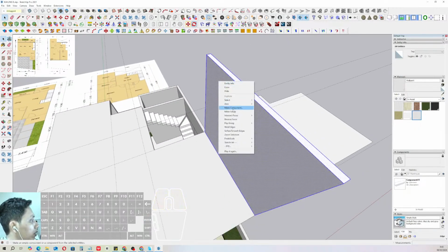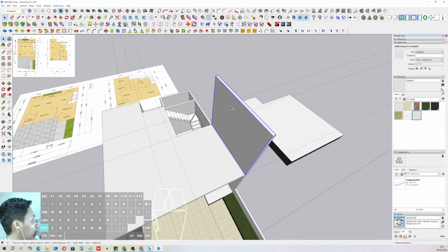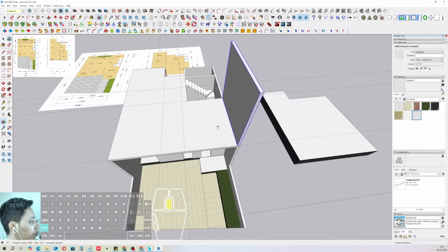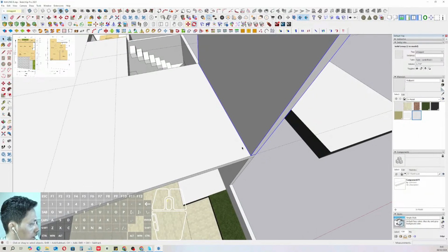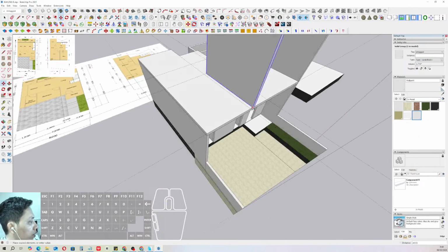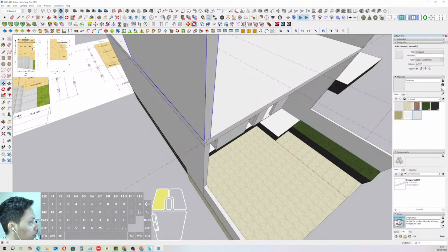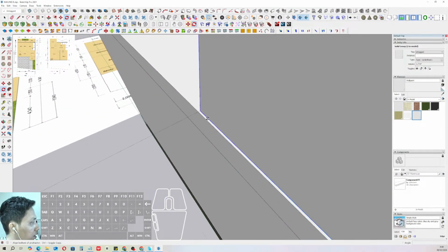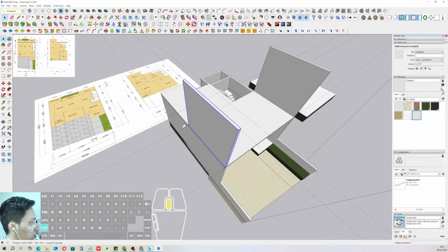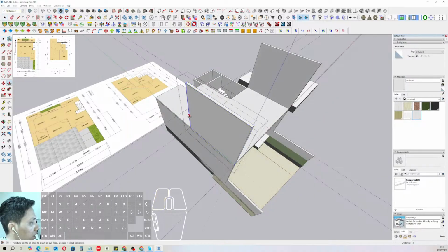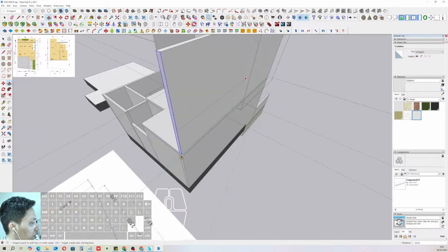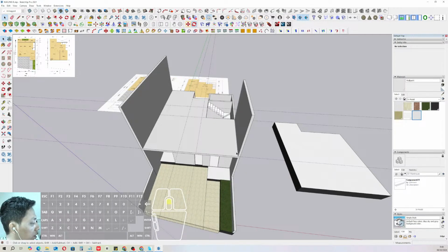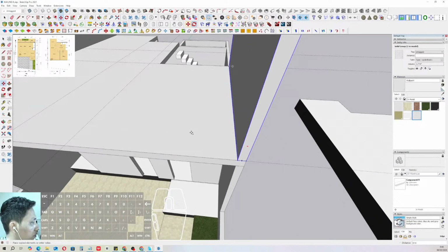Then we can triple click, make group, and select the wall pane in here, and we need to adjust the wall orientation on this position, especially because it's a special condition with the unique direction of this wall side, with a little diagonal position in here.